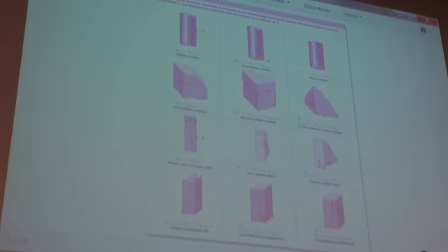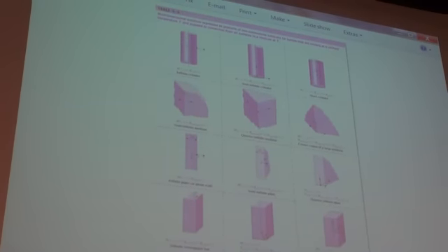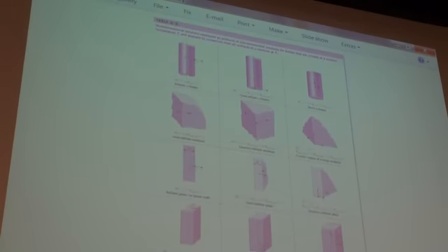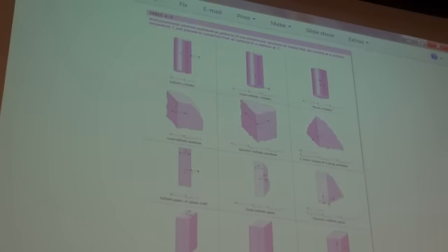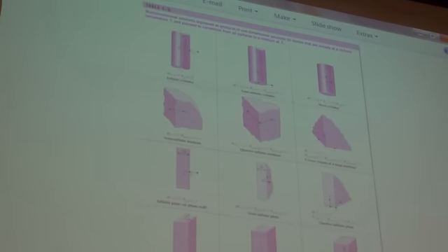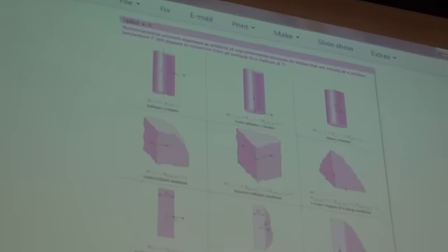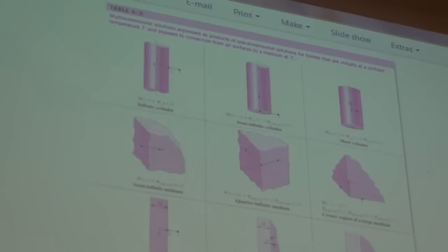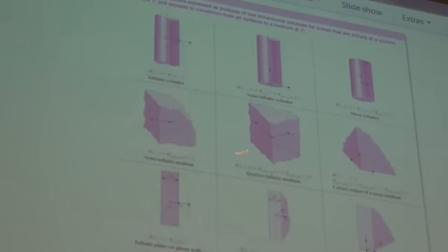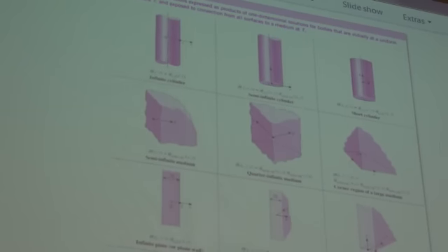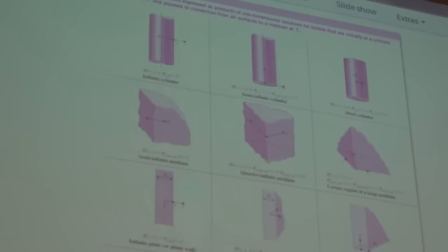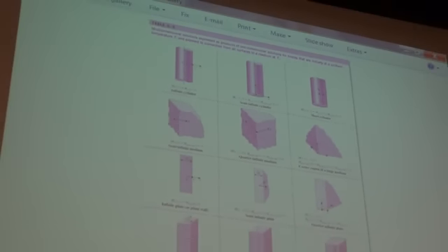Now, if you look in Cengel, in table 4.5, Cengel and Ghajar, you will see 12 different geometries there, which were all generated by this principle of superposition. If you are, for example, interested in the rectangular bar, if it's a very short one, then that is the solution. If it's a very long rectangular bar and you're not interested in what happens at that surface and at that surface, then it would be equal to that one.